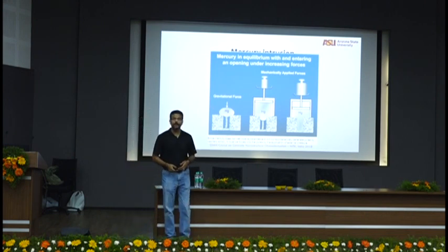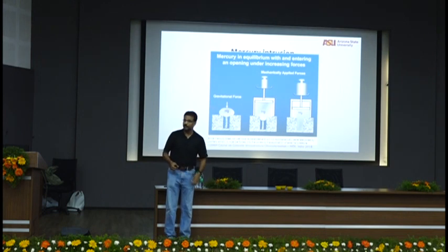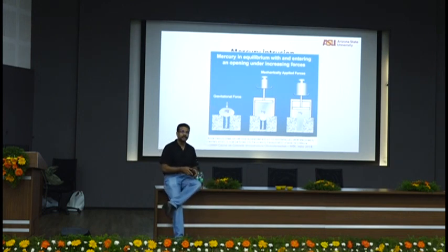But there's a problem. Concrete absorbs water. So I cannot use water as a fluid to fill in. I want a non-wetting liquid. The only non-wetting liquid that we know of is not very friendly, not very healthy, but we have no choice. Mercury is the only non-wetting liquid. Problem with mercury? Extremely high density. So you have to squeeze it under extremely high pressure into the structure.